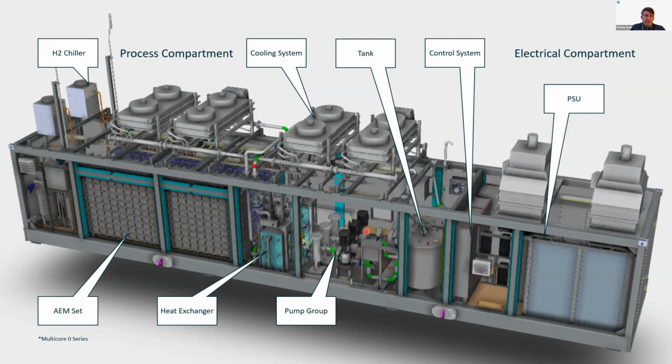Here you can see the pump group. We have in total 3 pumps. 1 is a backup pump. This is required, or it's not required. We would like to have a high reliability, and if a filter doesn't work anymore, then we can choose this pump, and you don't have to stop the process. Then you can easily maintain the other pump while you have a backup pump here.